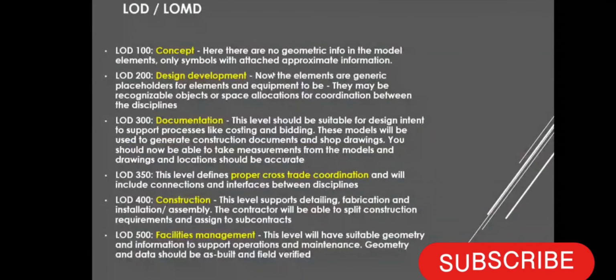LOD 200 is the design development stage of a project. Now the elements are generic placeholders for elements and equipment to be. They are not of accurate size or shape, but they are somewhat similar to a chair. For example, in place of a chair, you are keeping a stool. Then it is LOD 200. But in LOD 300, it should be a chair, and it should be dimensionally accurate.